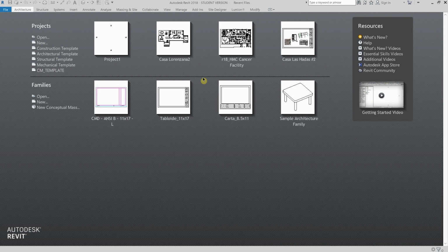First off, what is a project template? A project template is a starting point for all your projects. Revit comes preloaded with some templates that include basic plans and views, loaded families, and various settings. A custom template addresses specific needs you may have. For example, if you have a particular set of deliverables every time you work on a project, you can speed up your workflow by having your settings preloaded from the start.